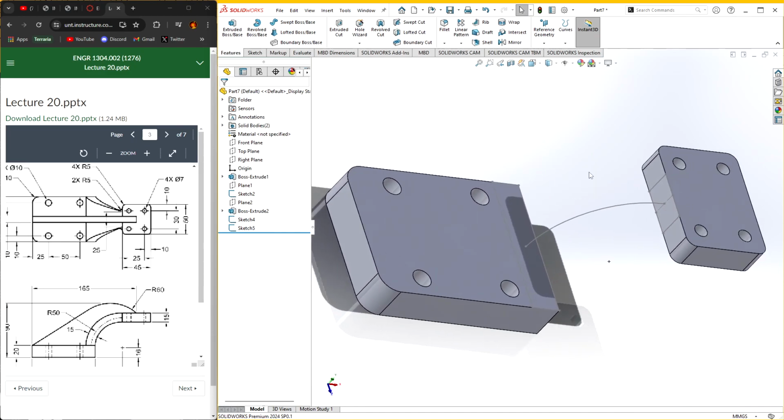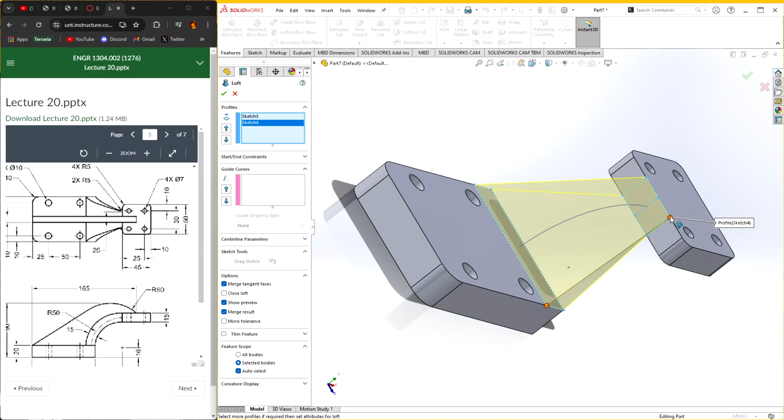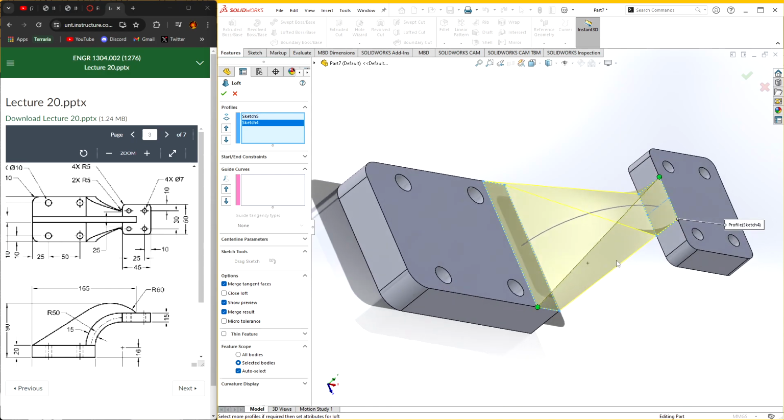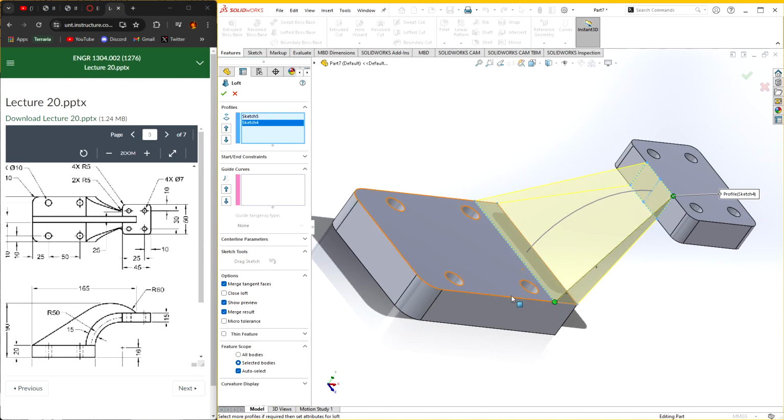So with this, we can do a loft between, let's do this point and this point of the sketch. If for some reason it becomes twisted like this, or it doesn't even show up like that, it's probably because of these green points. These are just to determine where the beginning and the end is for the loft. So I need this to be all the way over here on this side for this to be straight. Okay. So here comes the tricky part, right?